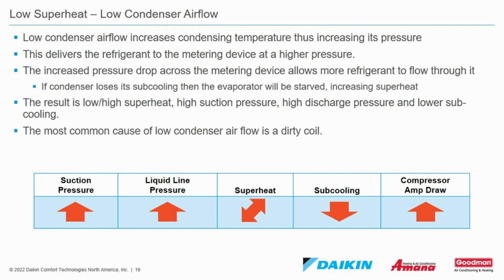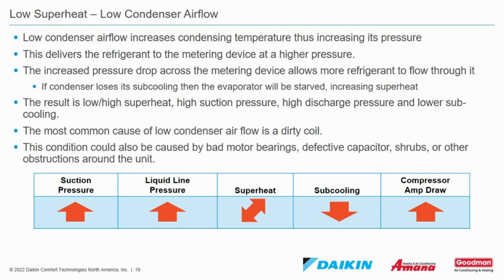The most common cause of low condenser airflow is a dirty coil. But this condition could also be caused by bad motor bearings, a defective capacitor, shrubs, or other obstructions around the unit.